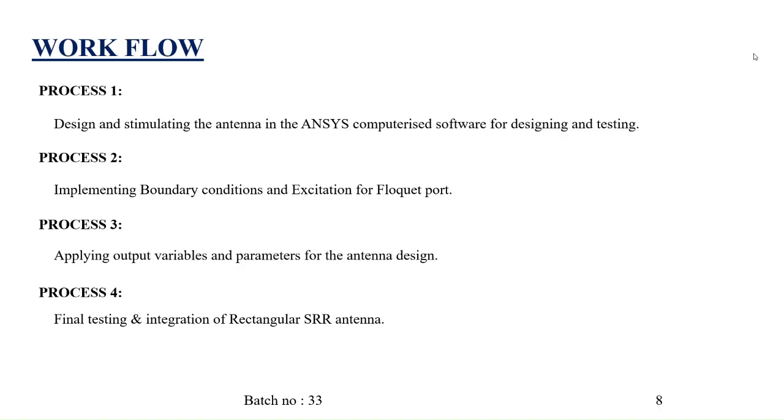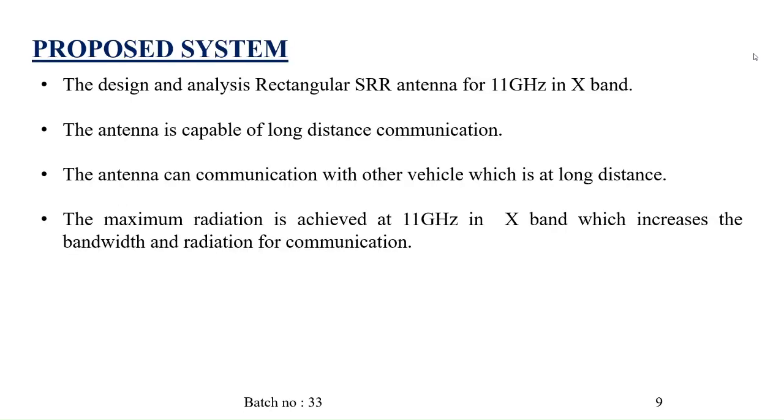Workflow. Our first process is to design and simulate the antenna in the ANSYS computerized software for designing and testing. Our second process is implementing boundary conditions and excitation of lumped port. Our third process is to apply output variables and parameters for the antenna design. Our fourth and final process is testing and integration of the rectangular SRR antenna.